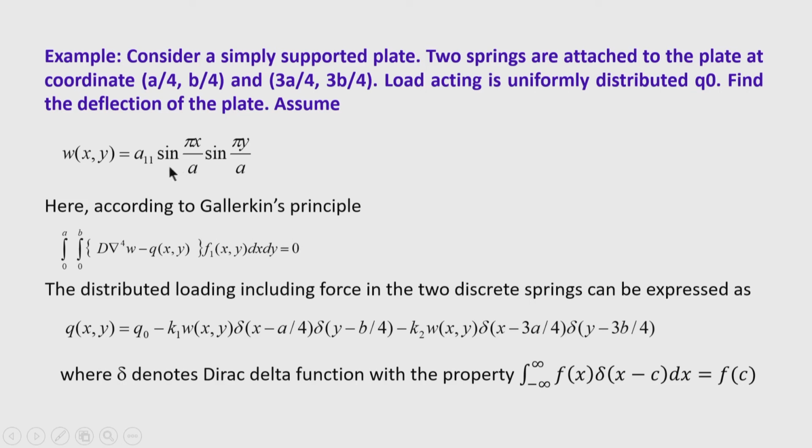Now, here we first carry out the integration of del 4 w into f 1 x y; that integration is the first integration I 1. Before that, let us show what is q x y. Q x y is the distributed loading on the plate. Distributed loading on the plate is given as q naught, as it is uniformly distributed, but there are also 2 springs attached at certain points.